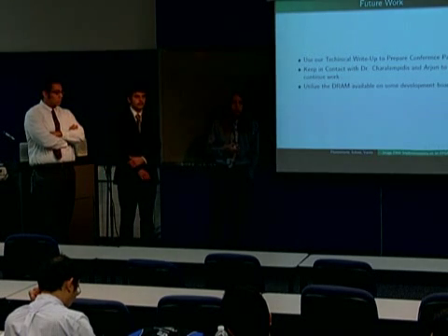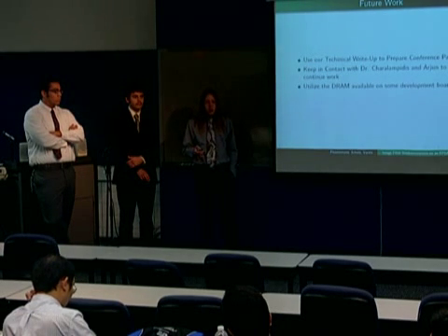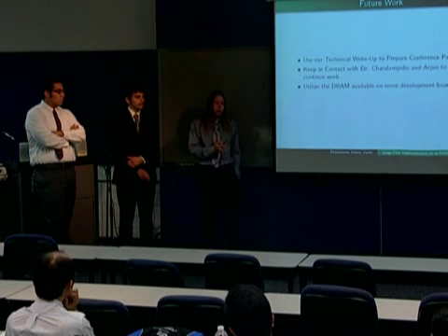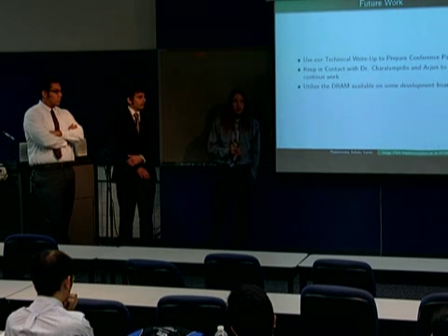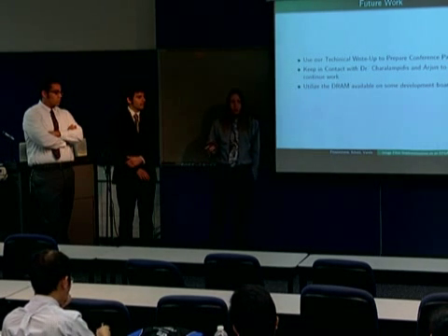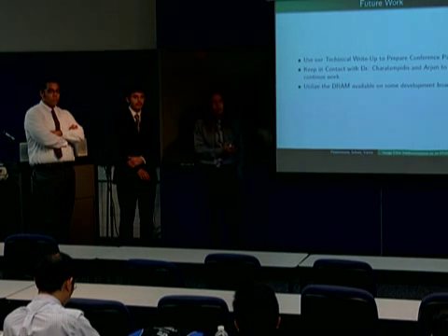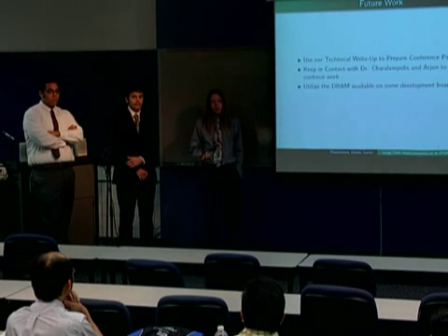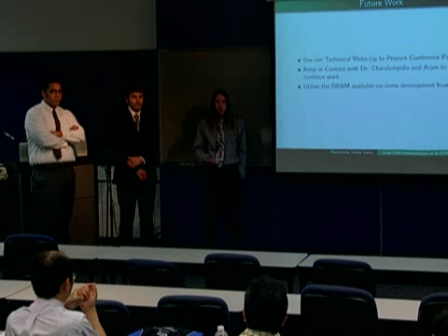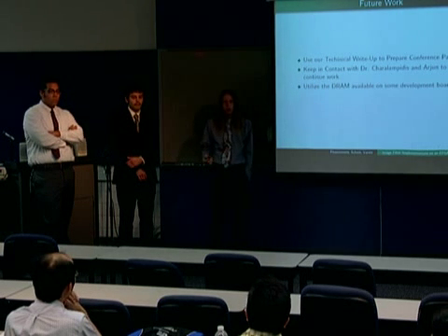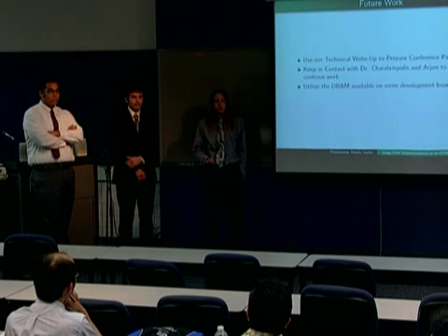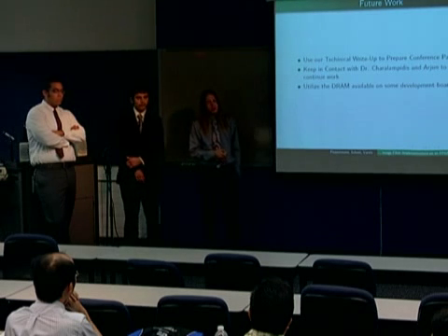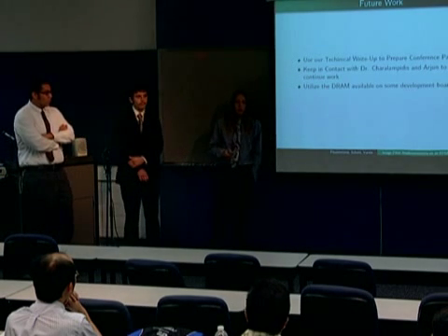So if we don't use our multipliers for multiplication, but we use, let's say we're using 5 multipliers and then we implement another 5 multiplications as lookup tables, then the other 15 multipliers go unused, but we're cutting into our lookup tables available on the board. So there's really no reason not to use multipliers when you're using multiplication operations until you run out of them. In that case, you'd have to move to multipliers or lookup tables. So it's just a matter of efficiently using resources, because lookup tables can be used for more than just multiplication, but multipliers can only be used for multiplication.